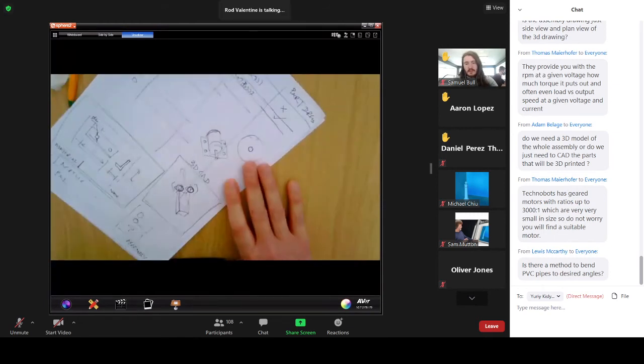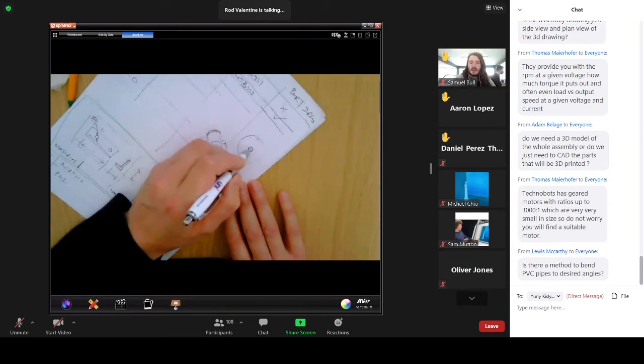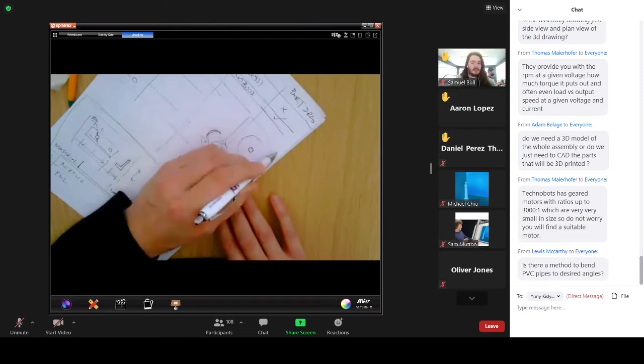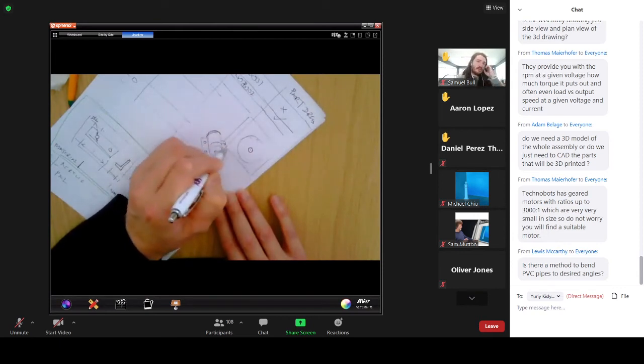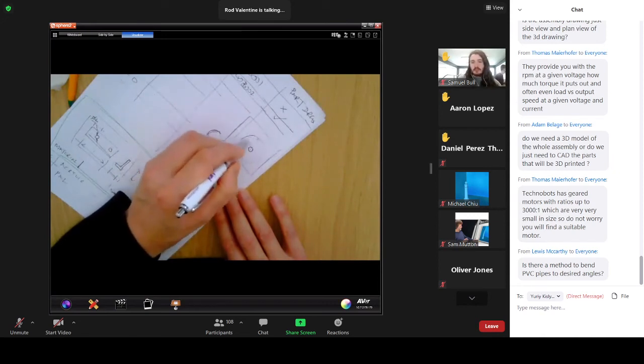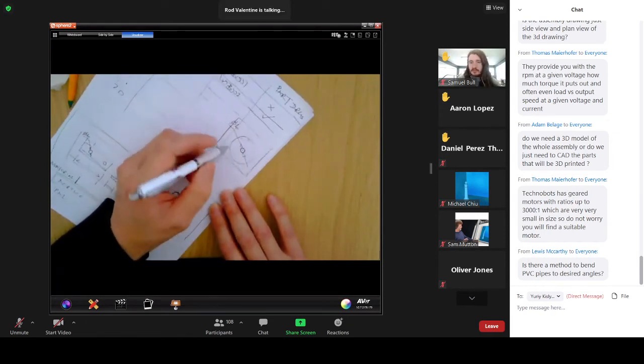If you've got a gear which has a bore that is smaller, then it's absolutely no problem to make that bore bigger. And then what you would do is please include that as a separate part drawing. Then you can specify on your drawing what your new diameter is going to be. That's diameter 6. Then you can create a drawing for that.